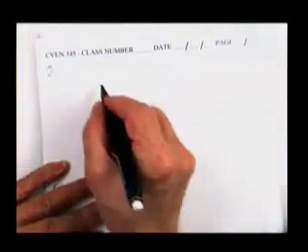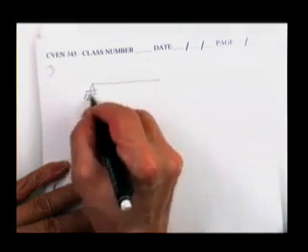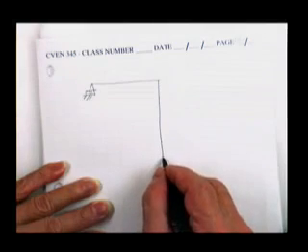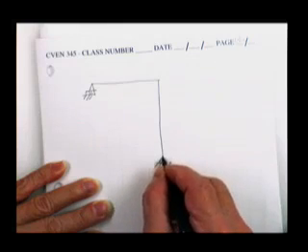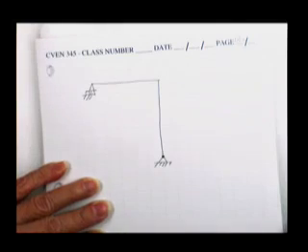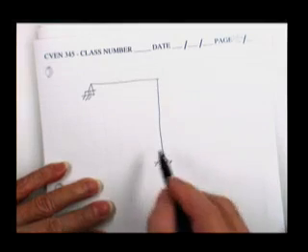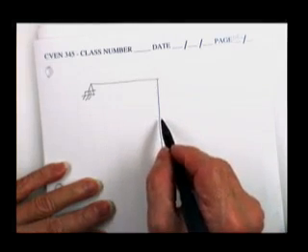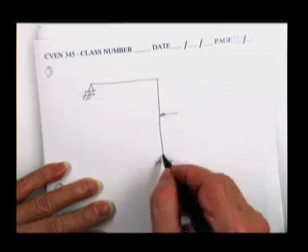So the complementary structure could have been, leave this on the roller, leave this down here, and turn it into a pin, thereby removing the ability of this thing to take a rotation. And then you would come up with, this would be your primary structure for everything else. Probably be a little harder to work with, not necessarily a whole lot harder, but for instance, here's the one for the real loads.